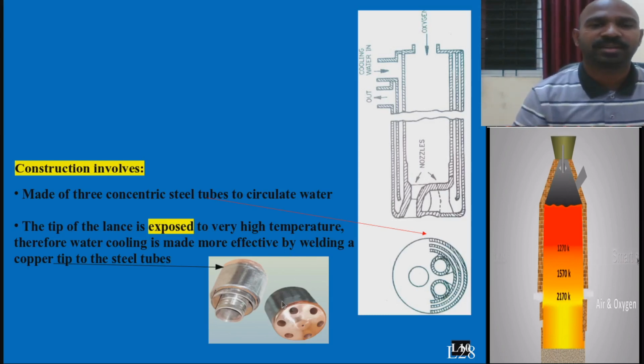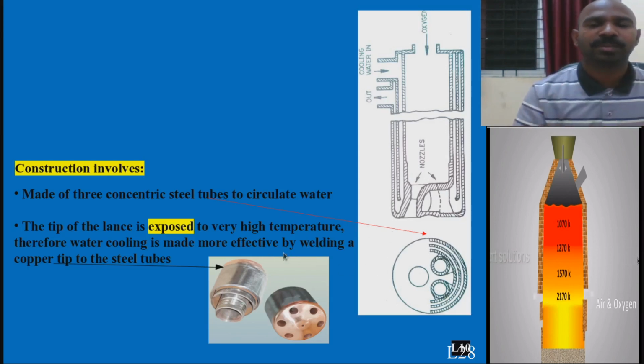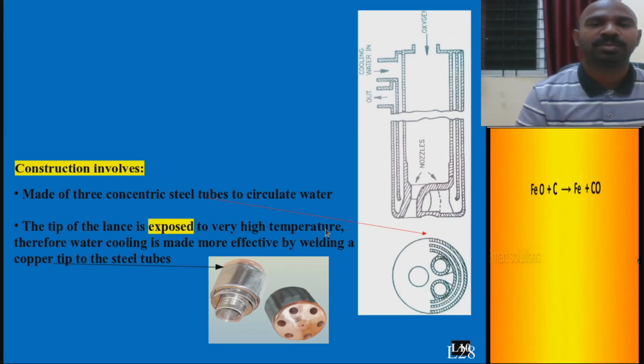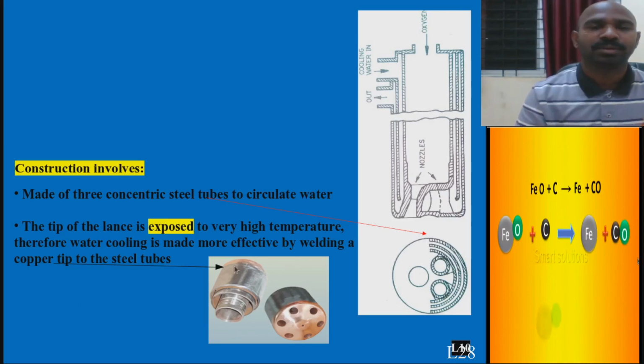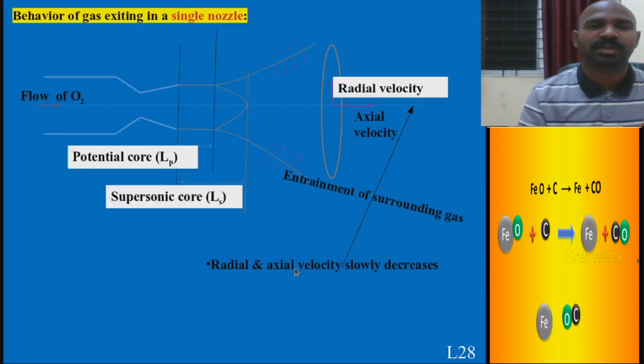Why? Because this particular oxygen lance is exposed to very high temperature, and because of the heat transfer and thermal conductivity to be balanced, for more heat transfer we use a copper tip on this.